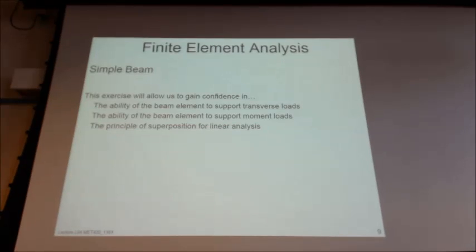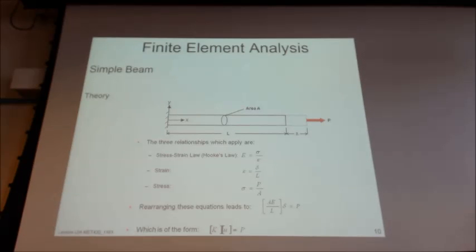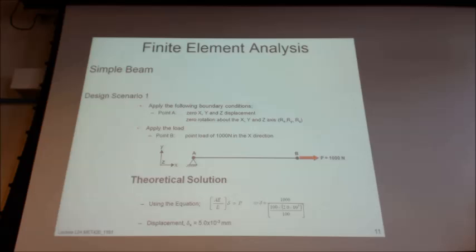And then we're going to develop or gain confidence in what the FEA program is doing. So to start out with, we'll do an axial load on the beam. We have equations to deal with that. We can solve for a theoretical solution, and those numbers are here. So we've solved for a theoretical result, and then we can plug it into Simulation Mechanical, and let's see what we get.